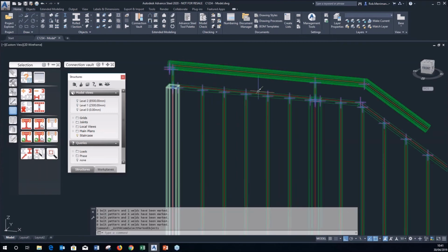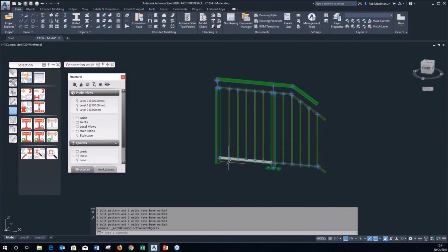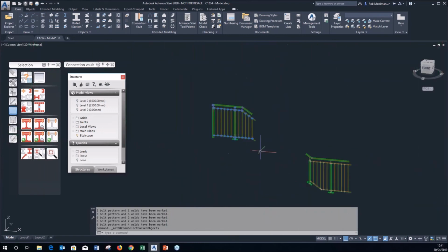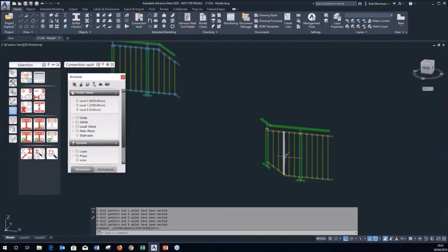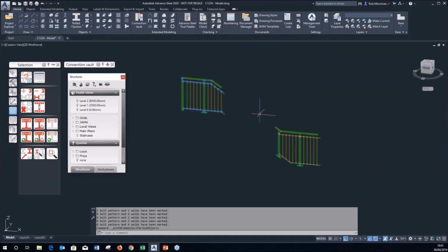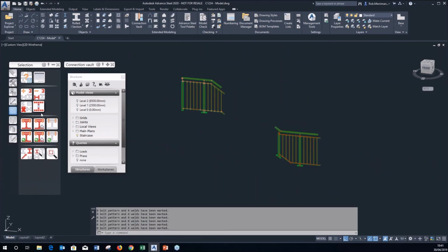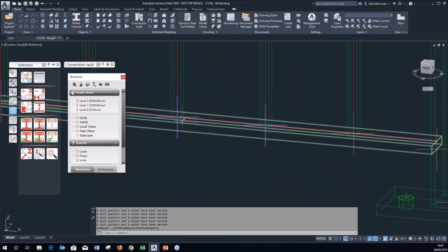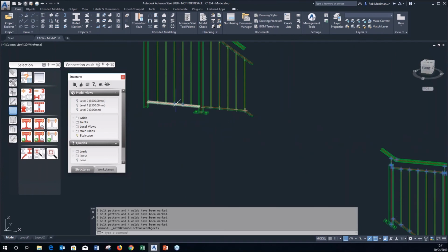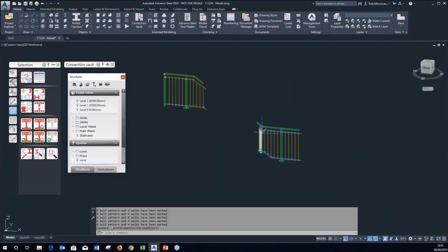And then you can see that all the welds in here go red. Nothing has gone red on this one. So there are no welds in this panel connecting these elements. So we can repeat the process on the other assembly. And this time, you can just see in there that those two welds are actually connecting items in this panel, which is what's causing me the error. Now, I know this because I deliberately put this in.